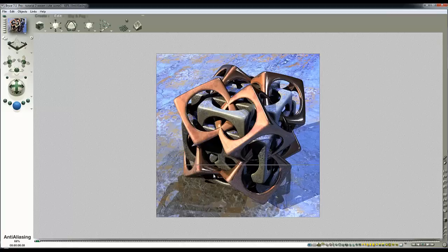But as you can see, if you're using the anti-aliasing paths here, it can take time depending on the complexity of the materials, because the anti-aliasing path looks at the level of noise in your image, and depending whether two pixels side by side are different enough, it will then start sending in more rays to sample that part of the image, which is why if you've got very noisy images, the anti-aliasing path will take a lot longer.